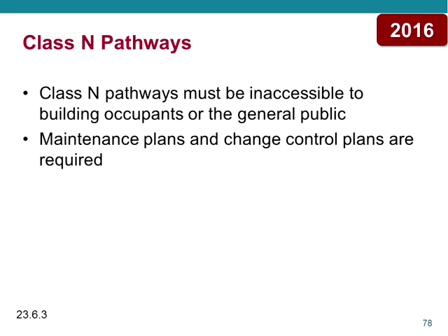Now, if we're using Class N circuits, obviously they have to be limited in access to people. We don't want anybody to be able to get their hands on the circuitry. It's a life safety system. I used to work for an organization that had a classified network, and that network was kept under lock and key wherever the circuits were available for tampering or maintenance or anything like that. So if you have these pathways running in a building, they must be locked up and not accessible to occupants or the public. So they have to be tightly controlled because, again, it is a life safety system.